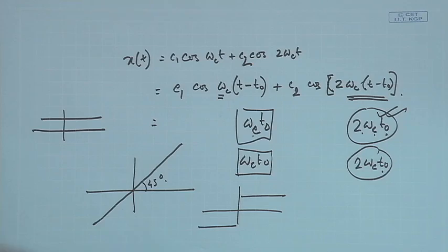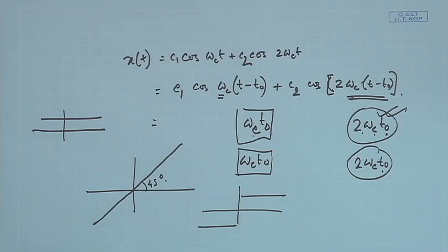So this is very easy to realize, any real circuitry will give you that, as long as it is not touching the amplitude. Whereas this one is harder to realize because it has a frequency selective delay. Different frequency elements get different amounts of delay. The phase shift is the same. So this is circuitry which is very difficult to realize.